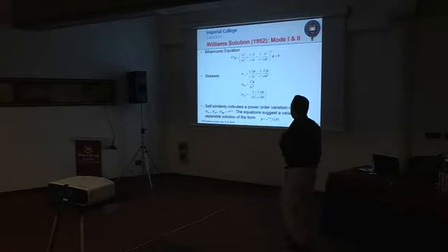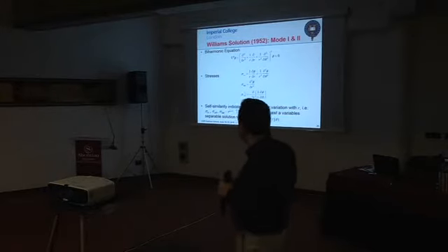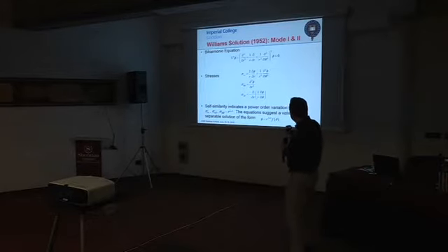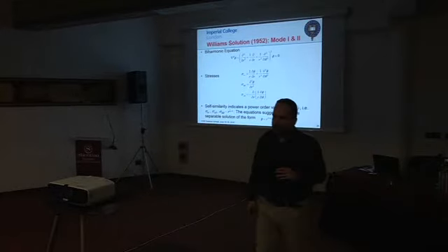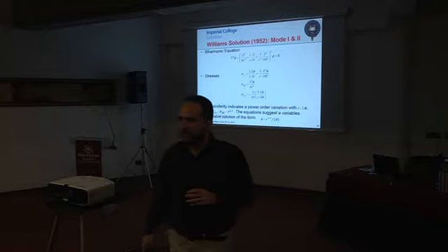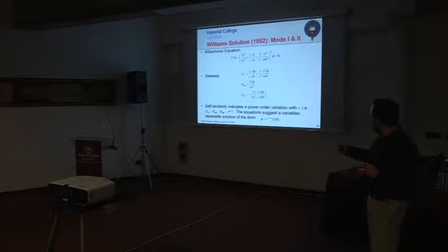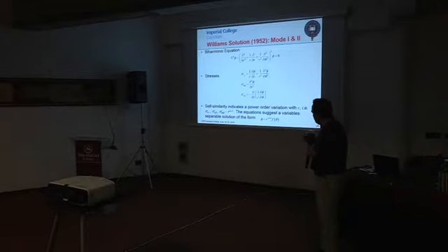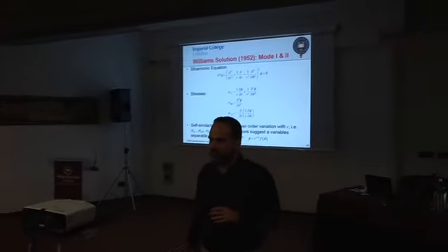It comes from here. Obviously, to solve the problem in elasticity in solid mechanics, you usually start with a biharmonic equation, and then you say that the biharmonic equation, in this case, is going to be an equation in r and theta, and phi is the potential function, the Airy stress function, that you want to find that solves the problem. So if that is the way you write your biharmonic equation, you can actually define the stress field as a function of the derivative of those stress functions.